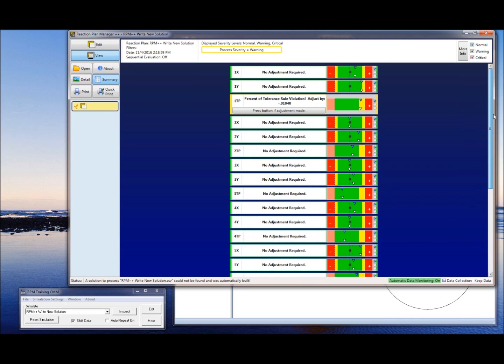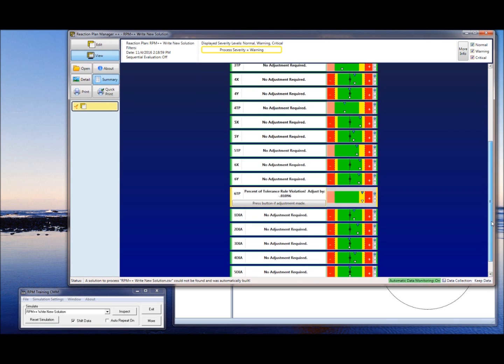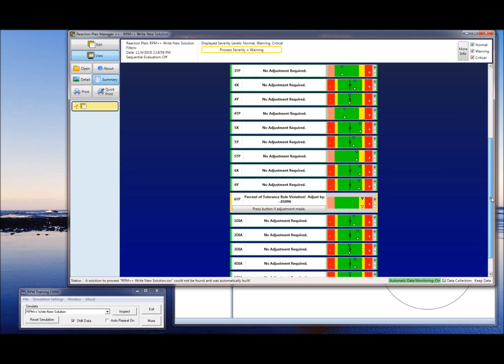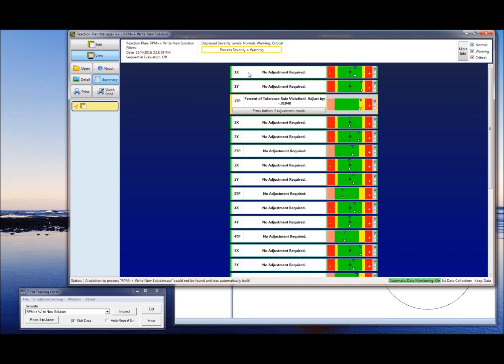So when you're using the software, the bolt pattern analysis software needs the linear locations of the holes as well as the true positions. It doesn't necessarily need the diameters, that's optional, but at minimum you need the linear locations and the true positions.